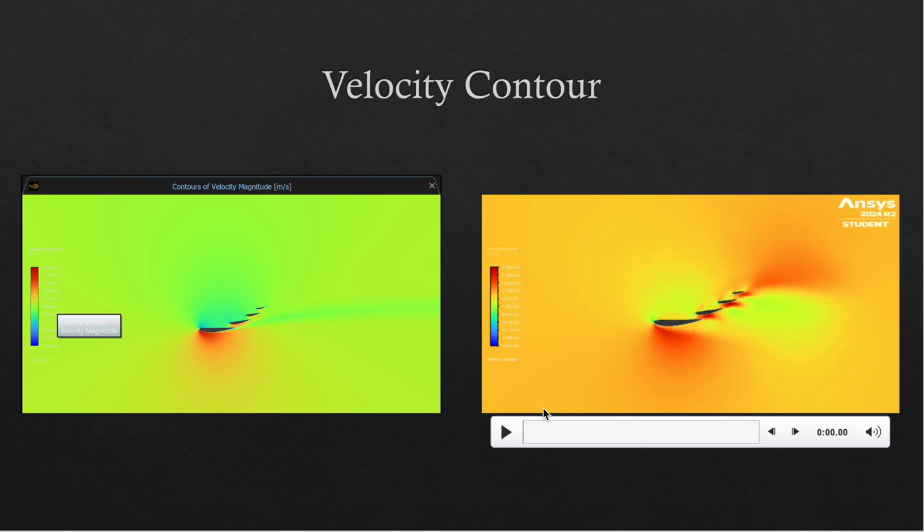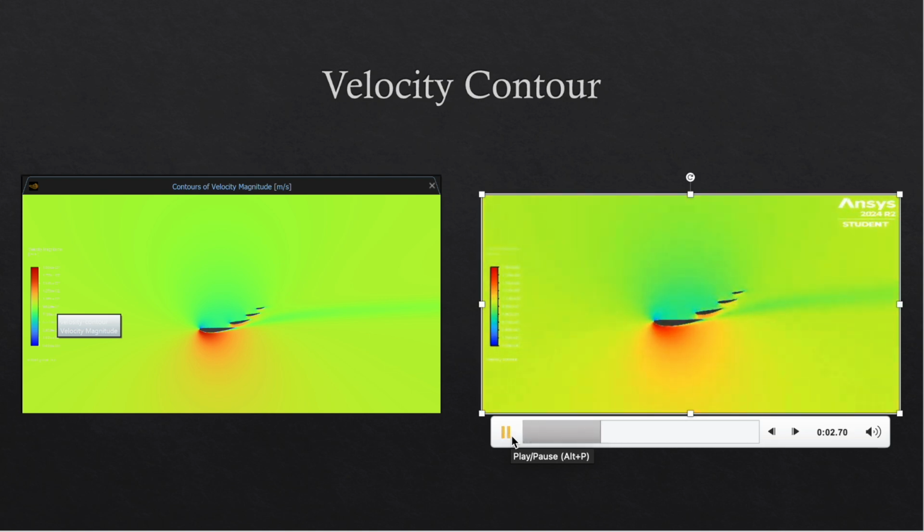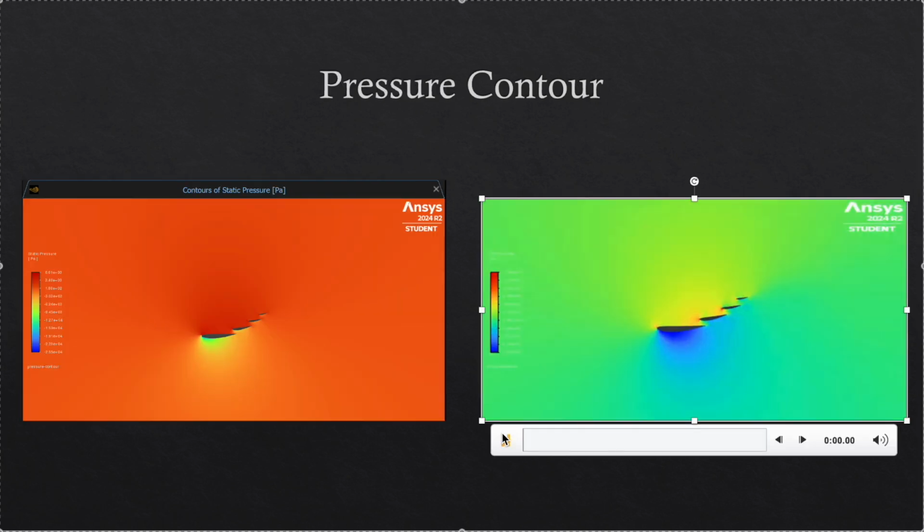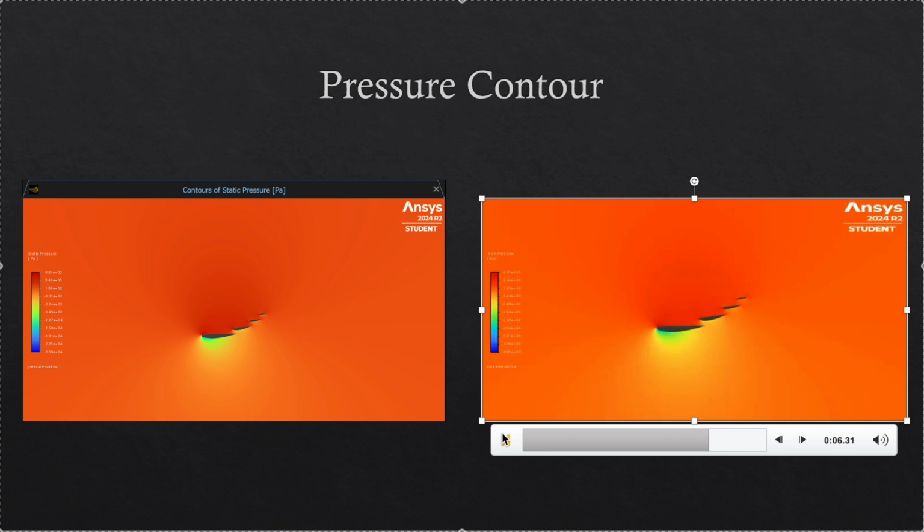The velocity contour revealed how air moves under the wing surface, particularly under the bottom surface, which created downforce. The red is the faster high-speed air, whereas the blue is the low-speed air. As you can see, the trailing air comes out smoothly, which indicates good aerodynamics of the wing. Pressure contours provide clear evidence of high pressure zones on the underside and low pressure zones on the top, confirming the effectiveness of the wing in creating downforce while managing drag.